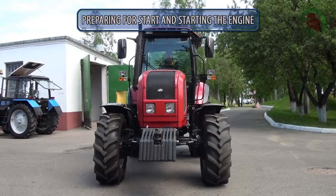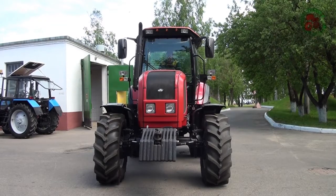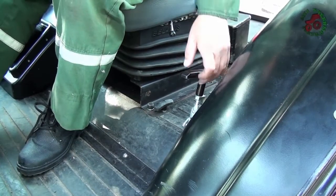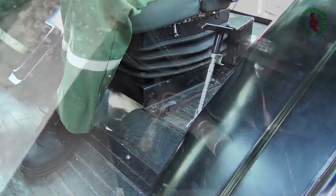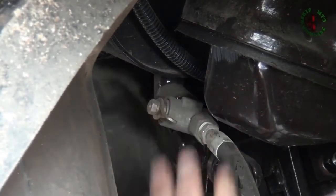Preparing for start and starting the engine. To start the engine of Belarus 1522-2022 tractors, carry out the following actions. Engage tractor parking brake. Open the fuel tank handle.